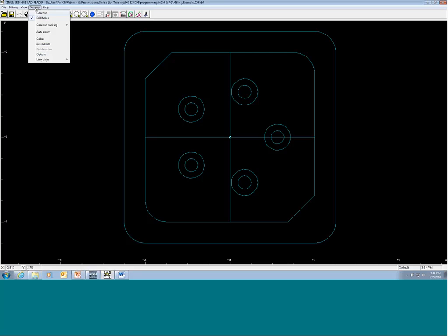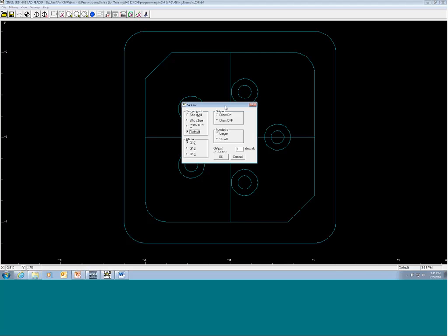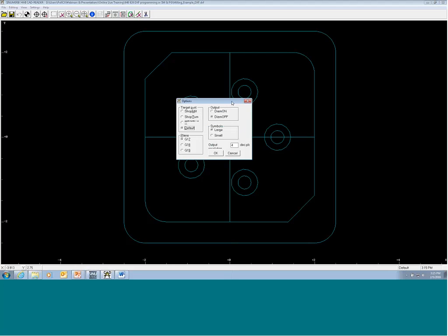I got into a scenario where I was pulling up my options window, and it wasn't here, and I thought the software was actually locking up, because if you click on the outside of the option window, you can't access anything because the window's up. But the window was actually way off the screen, and I couldn't get to it to bring it back on. So I found, through Google, our best friend Google, that if a scenario like that happens, you do an Alt and spacebar routine, it will give you a pop-up, and then if you click on the Move option and use your arrows, you can move around the window. So I was able to jog the window back into the display area.